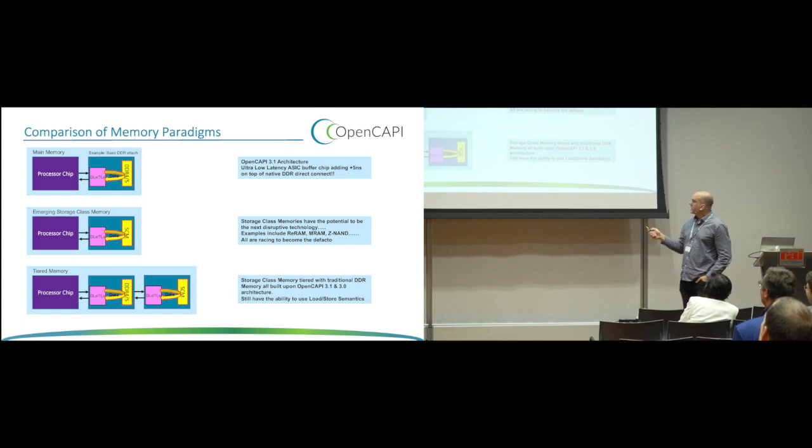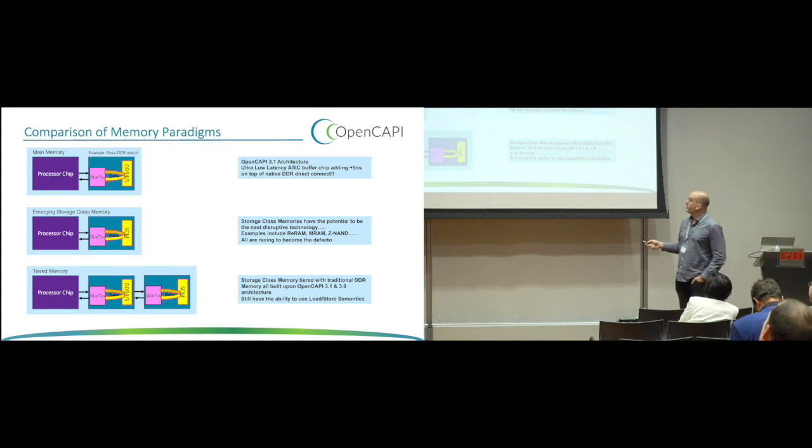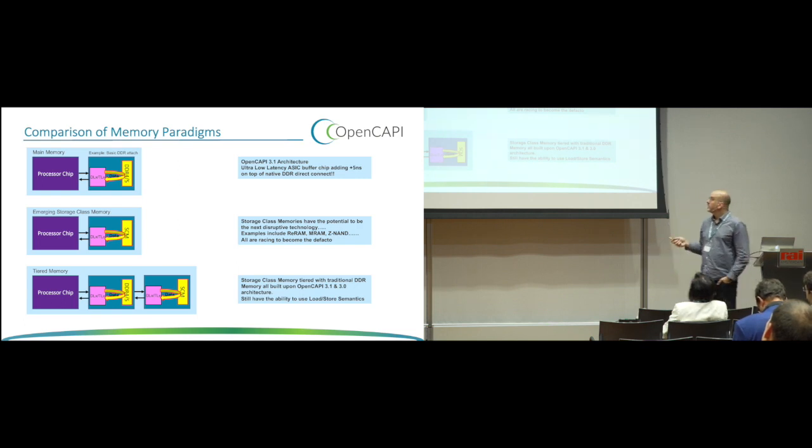Here it shows the continuum. With the OpenCAPI interface, you plug in one of these, which is memory, just DDR buffered memory going into a slot. Maybe instead of memory, you want to plug in something that has non-deterministic latency. Here the latency goes out. DDR is pretty deterministic and pretty short. But what if you want to go to something like SCM that may have really long write latencies? Another thing to talk about, especially relative to DDR, is that writes on this interface are explicitly acknowledged.